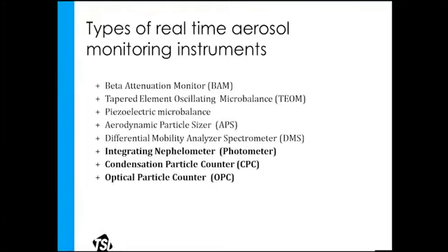Then there's a couple others. There's particle sizers, differential mobility analyzers. TSI makes some of those. These are the research instruments. So when they're doing studies, you read about the studies of how many of this size particle was emitted from the tail end of a Volkswagen. Well, that's probably false because you read the wrong information if you saw the reports recently. But there are research instruments. These are in the lab. A car will be mounted to a rack, running at a controlled engine level, and there's exhaust hooked up to ventilation, and you're measuring particles coming out of that exhaust. So an aerodynamic particle sizer will tell you exactly how many particles of what size you have. They're expensive. They're research level stuff. They're not easy to use.